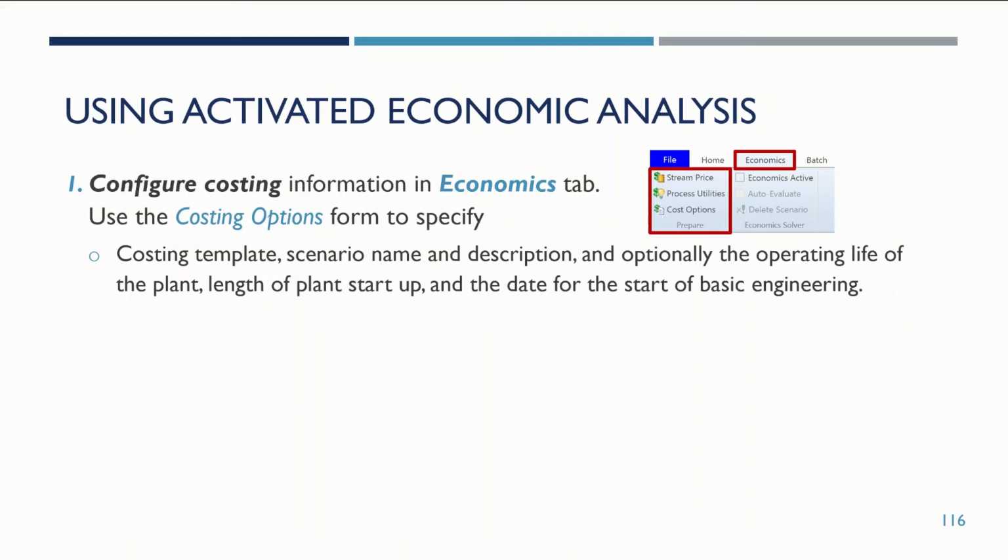The costing template determines the units of measurement and currency used by APEA, as well as the schedules used for calculating costs and other options. This may differ from units and currencies used in ASPEN Plus. Pre-configured templates are available for several locations around the world, with appropriate currency and cost schedules, each in inch-pound, or IP, or the metric units. You can build your own template in standalone APEA to specify these and other options.